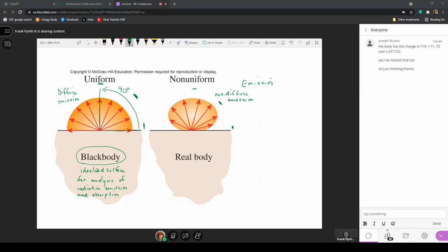If I'm moving through different angles and I get different values of the heat flux, then that says that there is a directional dependence for the radiation heat flux, in that if the surface has a non-diffuse emission associated with it, then I'm going to get different values of the heat flux as it's measured as a function of some angle variation from this particular surface.